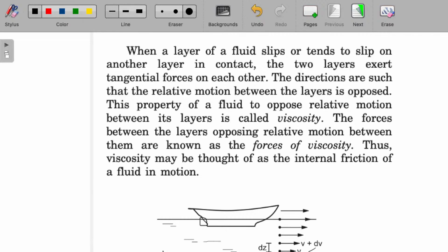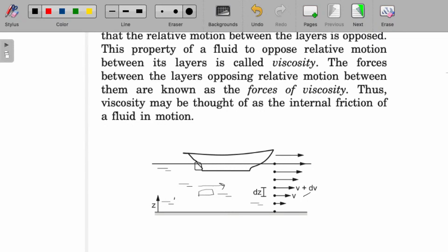As the fluid flows, the flow of the top layer on the bottom creates a certain friction. So that friction leads to this value of drag force, which is equal to eta A dou V by dou Z. So the A area is basically the area of the fluid that you're considering, right? So let's say you take a layer A of the fluid area and you have another. So due to that, you want to find out the value of the force of drag. So that value would be equal to eta into this A into the gradient which you have for the velocity, right? Because one layer is static and the other layer is moving. So there's a small gradient here, dV by dz, for the velocity.